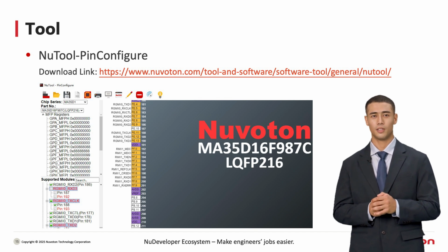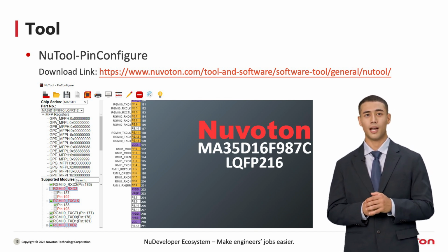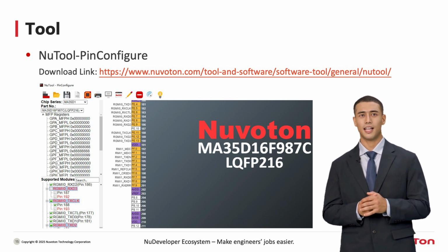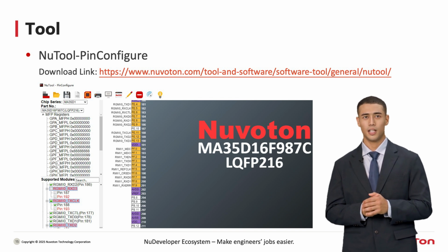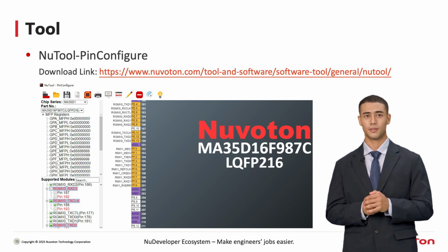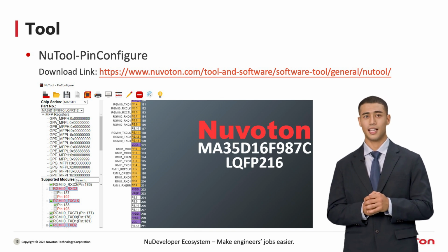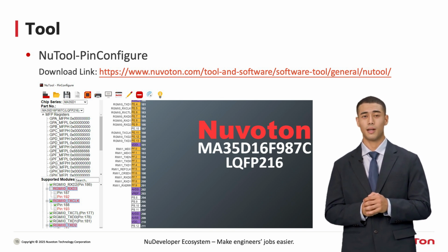PinConfigure is a software tool that assists in quickly configuring the functional pins of a microcontroller. Through this software, you can allocate the interface functional pins corresponding to the chip resources according to the project requirements. It is intuitive, fast, and error-free. Additionally, it allows you to save or import configurations for further editing and can generate initial pin configuration programs.